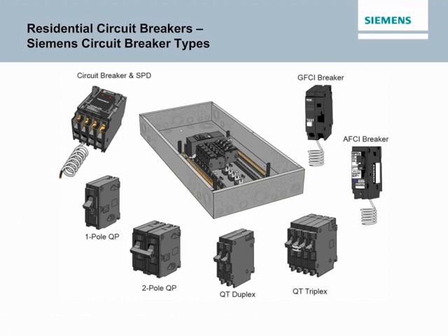In addition, the thermomagnetic circuit breakers, intended for use as main or branch circuit breakers in residential applications, Siemens offers branch circuit breakers with arc fault circuit interruption, ground fault circuit interruption, or point of entry surge protection. Circuit breakers are also available for a number of special applications. All Siemens residential circuit breakers provide overload and short circuit protection. Because of the variety of circuit breakers offered, this course describes only representative examples.